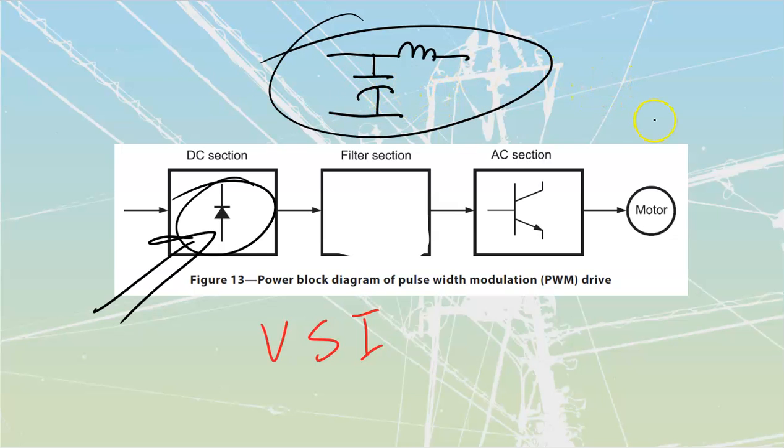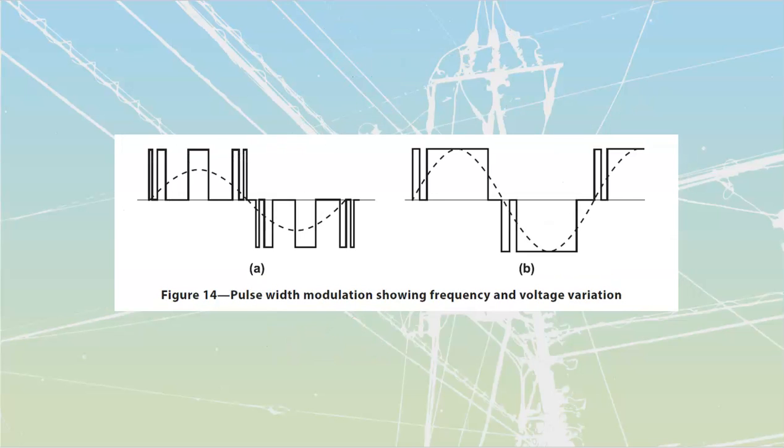We are going to have different types of switching often. This is the more modern one. We're going to have transistor switching, primarily IGBTs at this point, that we are going to switch out to the motor. And what we do is we switch out the full value of voltage to the motor. But we do it in little pulses. That's why we call this thing PWM.